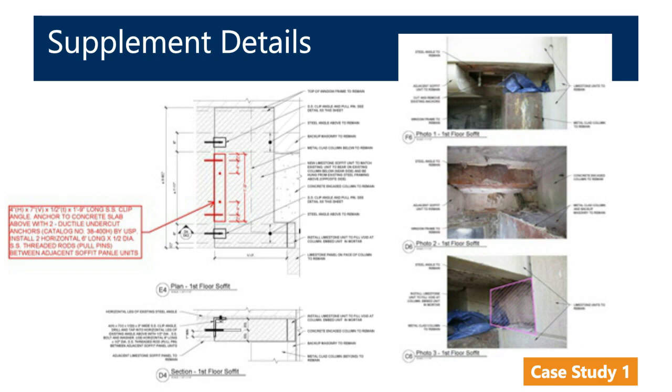If you run into a one-off condition, again, timely response: the AE's out there on site, the contractor opens something up, one-off condition, you say, okay, I'll get you a detail, but perhaps you can use the same number of anchors, same type of anchors that the contractor already has. It might fit within the unit cost, or if it doesn't, you prepare a change order and get that to the owner in a timely fashion so they can keep on track with what's going on and how the process is going.